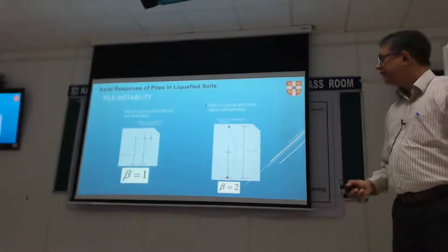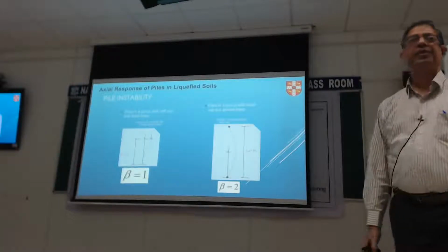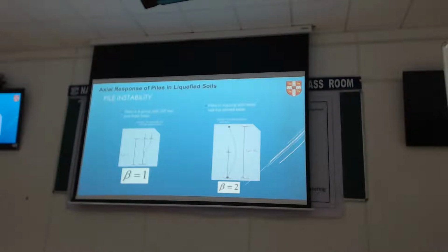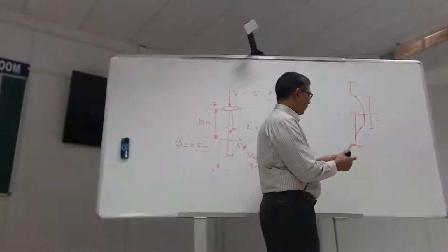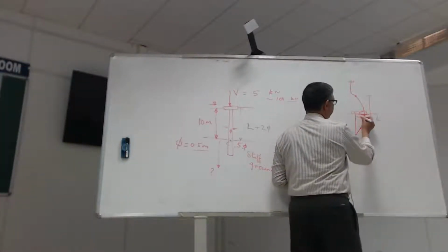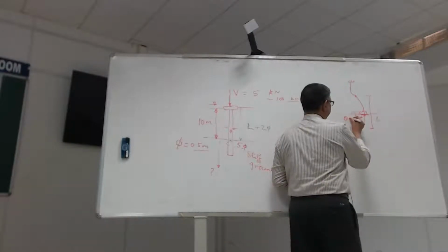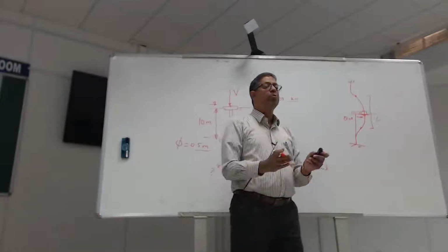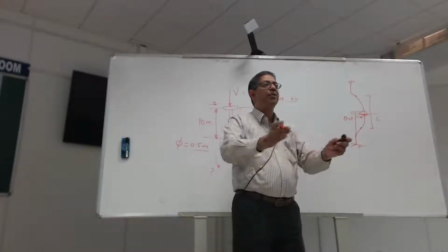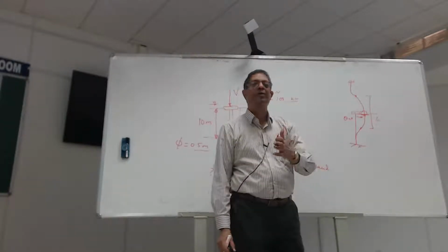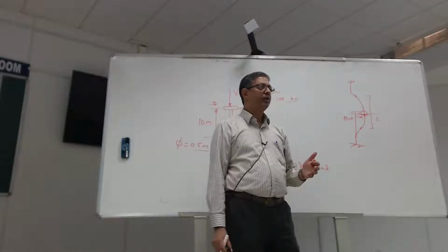As I said before, if I draw the full mode shape for fully pinned joints, you will get 2. There will be other cases also where I'm allowed no movement and no rotation. Here I'm allowing this thing to displace but no rotation, right? So it's translated there, but theta is 0. This can be the case when I have more than one pile. If I have a few piles in a pile group, then it's quite hard for the pile cap to rotate. We talked about this briefly yesterday also.